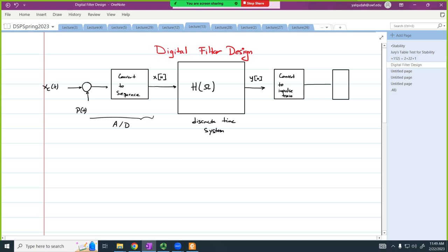And then I'm going to pass it through a low pass filter. And this is going to give me a continuous time y continuous of t. Yes, a low pass filter, because I have impulses. This is how we do the digital to analog conversion.